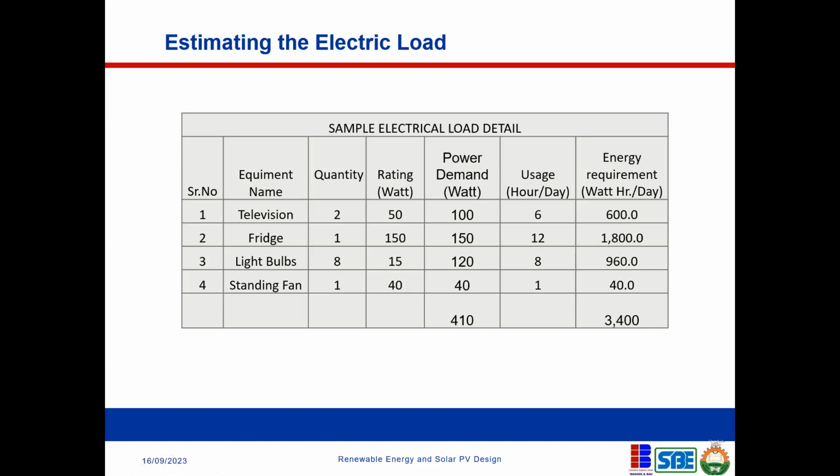Where you need to, do a load inventory for the things that need to be powered by the solar system. Then you also need information on the usage of those equipment, and this will enable you to size appropriately the battery that should be able to sustain those loads for the time that the client wants to use them.